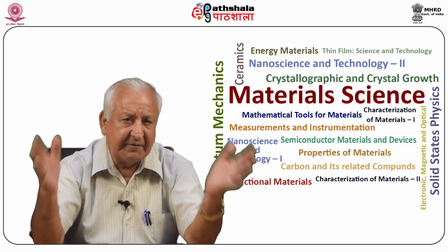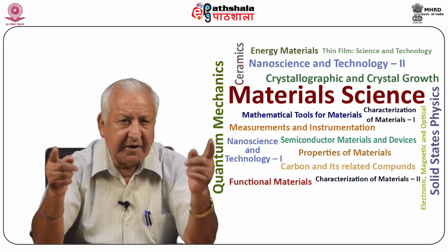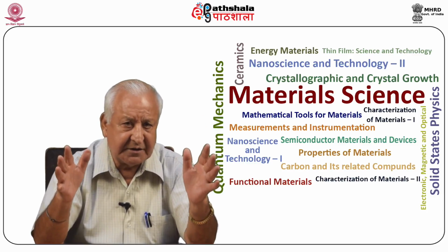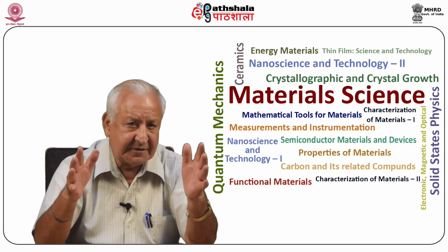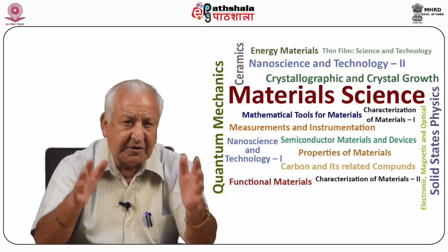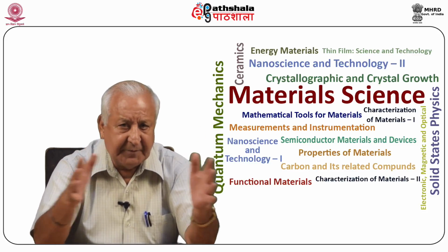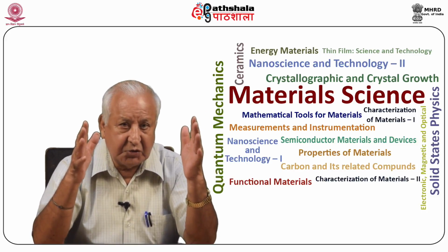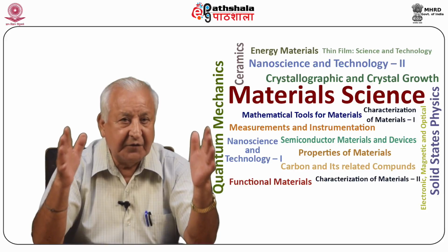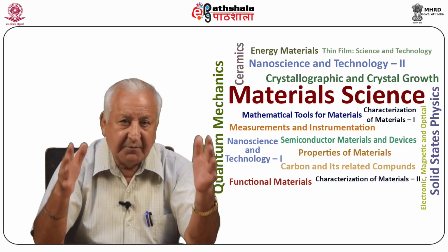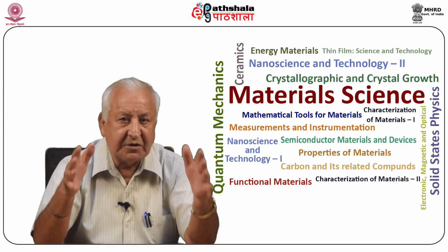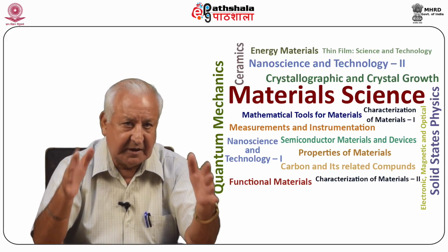Coming back to figure 17.1, regarding deformation of a crystal due to motion of dislocations on application of stress. When a dislocation of strength b sweeps over an entire slip plane, the two half crystals which meet on the plane become displaced relative to each other by the amount b in the direction of slip.